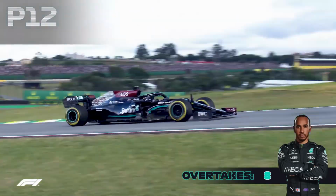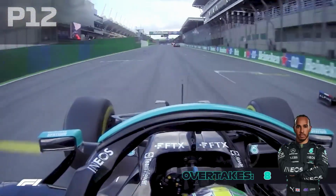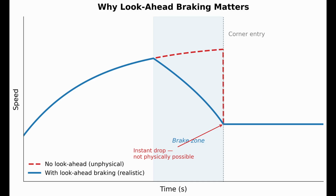Here's the part I want to spend a second on, because it's the most non-obvious piece. Look ahead braking. If the solver only checked the current segment, the speed trace would look wrong. The car would be at full acceleration right up to the corner entry, then instantly drop to corner speed. That's not physically possible. You need a brake zone.